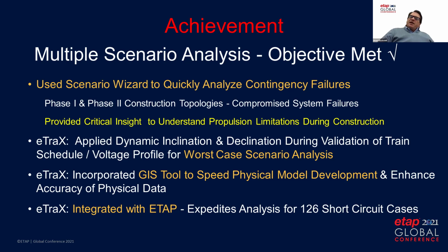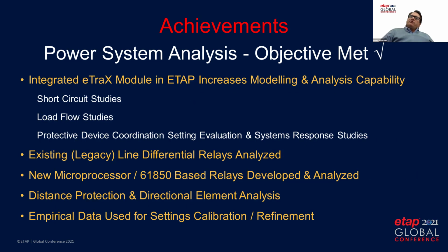The ability to integrate eTraX as a module with the ETAP software or the other modules within ETAP allowed us to expedite analysis of multiple short circuit case studies that needed to be done for this project. Those cases needed to be done to look at the load flow and also revision of the protection coordination settings that were affected by the construction.